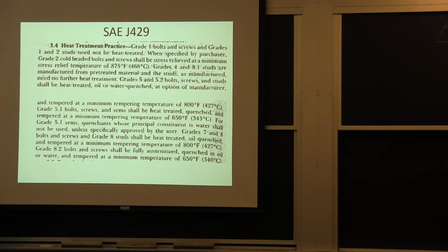If you really do it cold, you have a lot of residual stresses. You deform the steel in a way that when you let it go, it springs back and you have areas of compression and areas of tension. Now, if this was to go in a chemical environment where stress corrosion cracking will take place and other things will take place, it can happen underground, it can happen in a factory, you could start forming cracks just from the residual stresses.